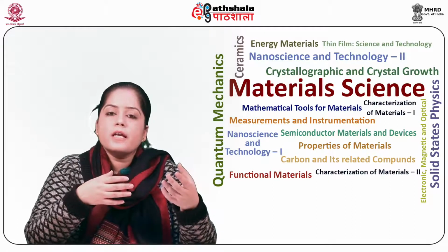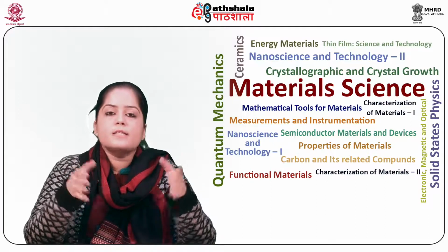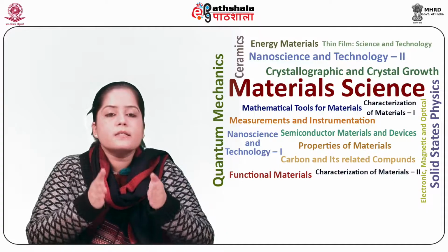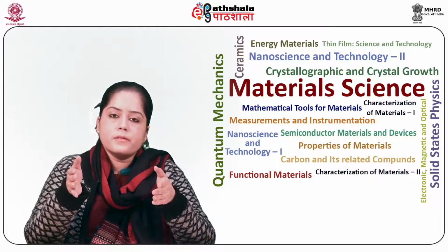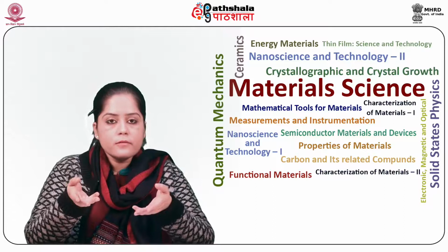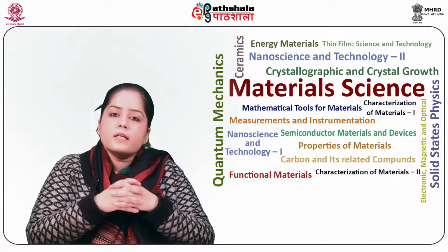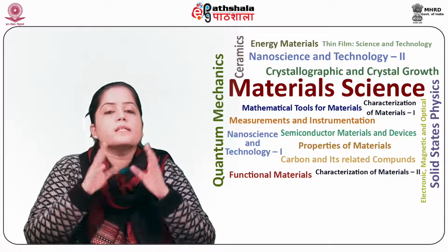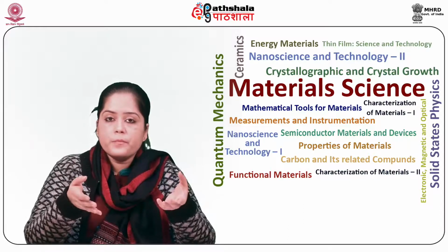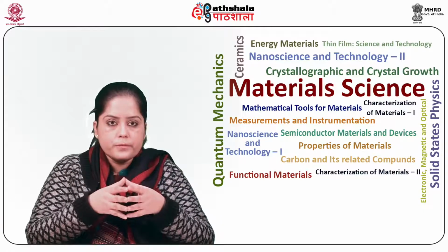Group 3 impurity elements such as boron are referred to as acceptors because they accept some of the electrons already in the silicon, leaving holes. Similarly, group 5 donor elements such as arsenic and phosphorus provide electrons. Silicon that contains a majority of donors is known as N-type, while silicon that contains a majority of acceptors is known as P-type. When N-type and P-type materials are brought together, they form a p-n junction.